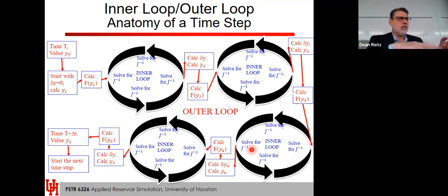Some of the reasons are that there might be a lot going on in your model, and sometimes it's a hiccup where you put a new well in and all of a sudden it's having a tough time solving. Most simulators today have algorithms that do this for you, so you don't have to worry about it. You put a new well in there and it might just automatically take smaller time steps. We'll get into time steps soon, because there are time steps that you impose, and time steps that the simulator will impose.